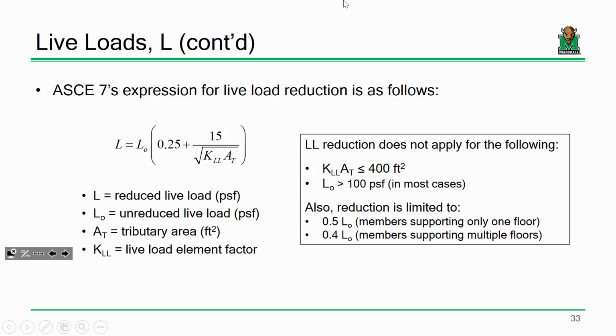Do you remember in structural analysis when we looked at that vehicle in influence lines, that vehicular model? That's the load that we use for bridge analysis. And bridges, if you're designing them for vehicular loading, are always going to see vehicular loading in some fashion or another. So that concept of live load reduction really wouldn't make sense for a bridge. It's a good question, though. Anybody else? This is good stuff.